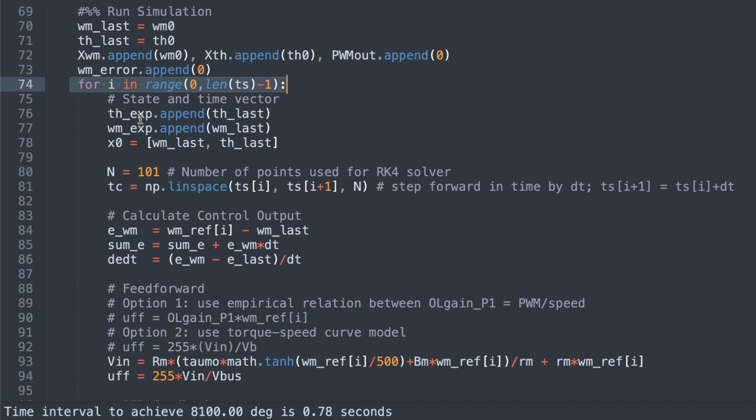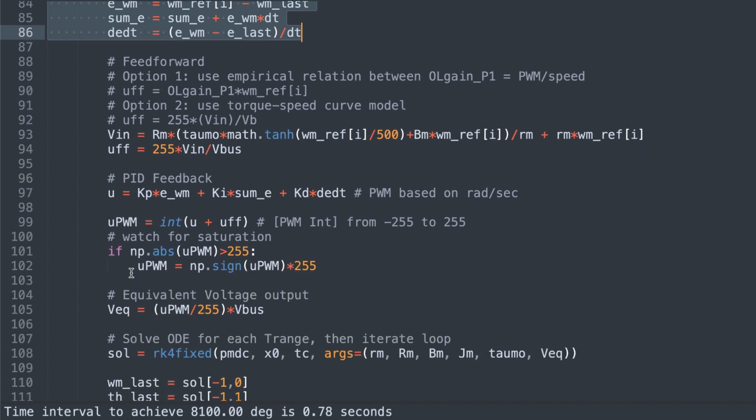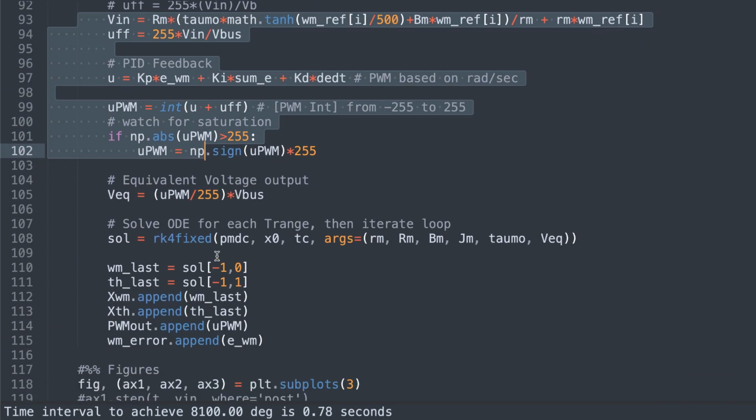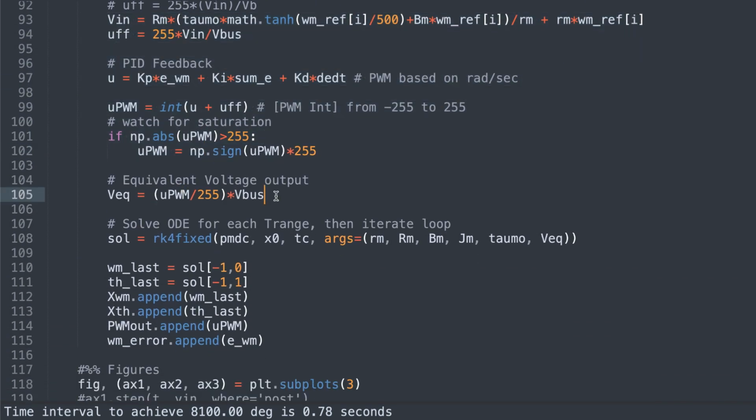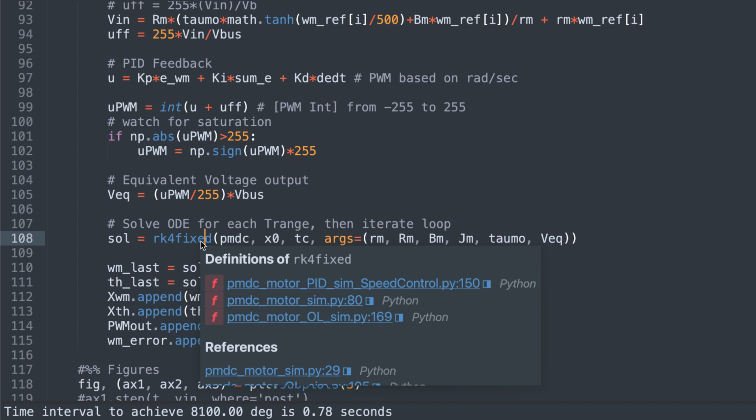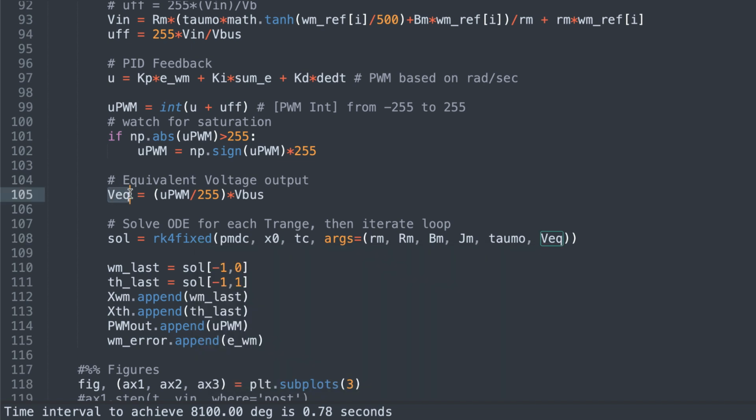So what it does is it computes all the terms, computes the sums, the delta t's, and here's what I was just showing you, the snippet. But then at each delta t, it runs a little RK4 simulation. Over that delta t, it integrates using RK4. See how it computes the voltage that is equivalent from your H bridge, and it sends that to the motor.